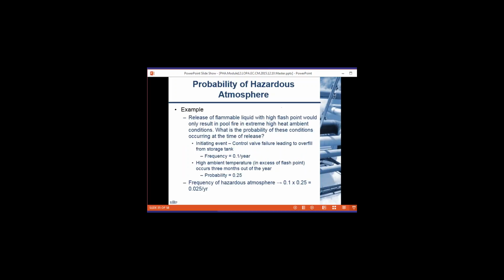A caution I state here: be careful not to double count IPLs. It's one of the examples I wanted to use. A lot of times you would bring up this modifier, flow rate, size of building, and you say, oh, we have, say, 6 air exchanges per hour, so we're not going to build up that asphyxiating atmosphere. However, a lot of times we'll have taken those air exchangers as an IPL. If that's the case, we do not want to consider that in our calculation of this conditional modifier.